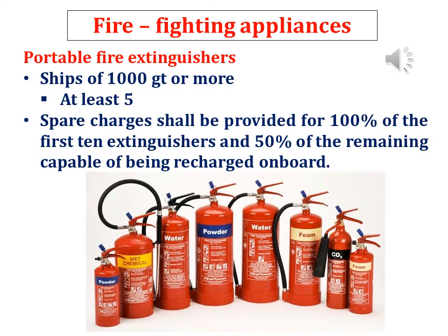Portable fire extinguishers. Ships of 1,000 GT or more. At least 5 spare charges shall be provided for 100% of the first 10 extinguishers, and 50% of the remaining capable of being recharged on board.